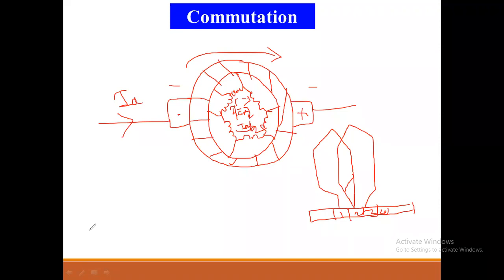That means it is towards the positive and it is away from the negative. Negative brush कडून positive brush कडे फ्लो होतो, त्याचंच meaning towards the positive, म्हणजे पॉझिटिव्ह कडे कुठून, निगेटिव्ह कडून. ओके, सी, so the current flowing through the armature conductor or the armature coil will reverse its direction when it is passing from one pole to another pole.